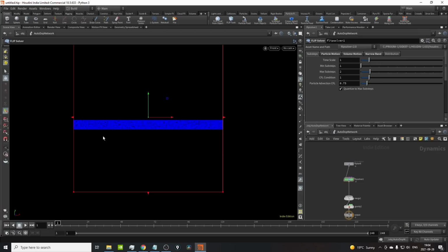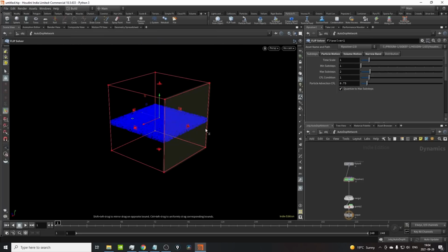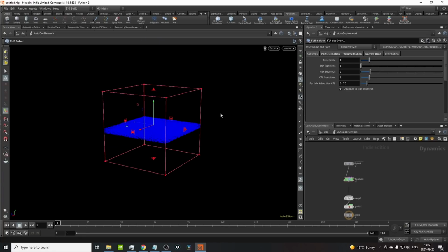Cool, so now we know the basics of the flip object, where to set the resolutions, how to set some solver settings, and how to make sure that our narrowband works and that our substeps are nice. We know where all of that lives. So let's drop in a little collision here and then export this simulation so that we can look at meshing and whitewater later on, right?